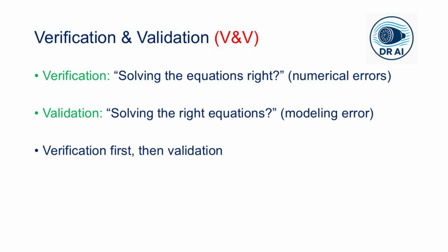In verification, the code verification, we find the bugs by the method of manufactured solutions, and we also verify the solution. Quantifying the numerical errors, which are the discretization, iterative, and round off errors, the grid convergence study, and the GCI are the verification tools.